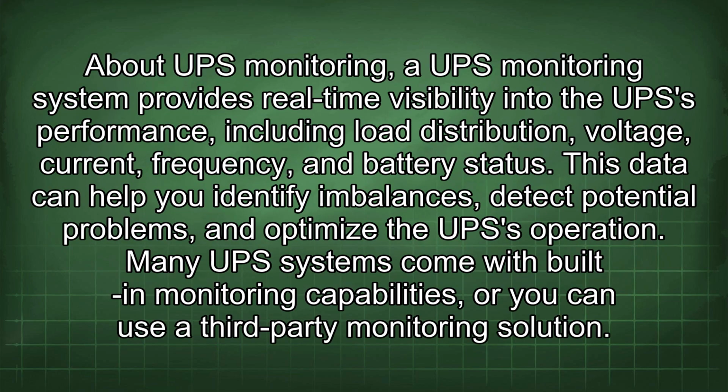About UPS monitoring, a UPS monitoring system provides real-time visibility into the UPS performance, including load distribution, voltage, current, frequency, and battery status. This data can help you identify imbalances, detect potential problems, and optimize the UPS operation. Many UPS systems come with built-in monitoring capabilities, or you can use a third-party monitoring solution.